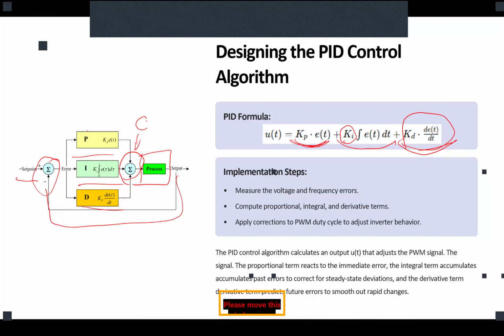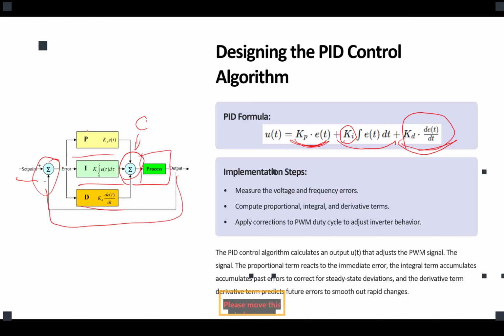The control signal would define, for example, what the modulation index of the PWM should be, or how much we have to shift the phase of our reference signal. Or in a PLL, how much we have to change the frequency of our reference signal. Those are the control leverages we had in PWM when we discussed PWM and SPWM.